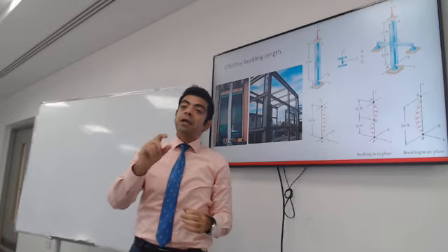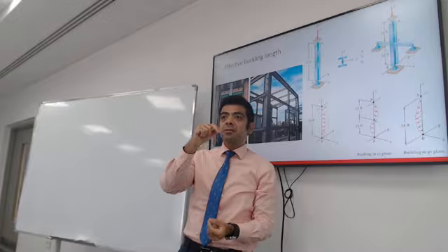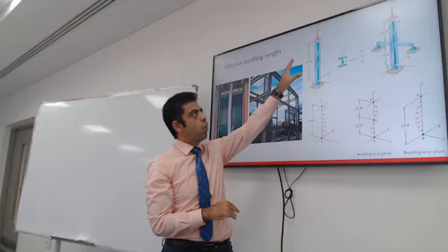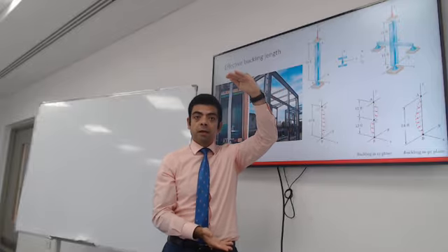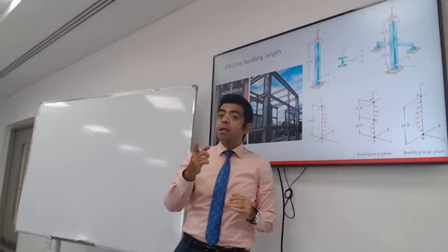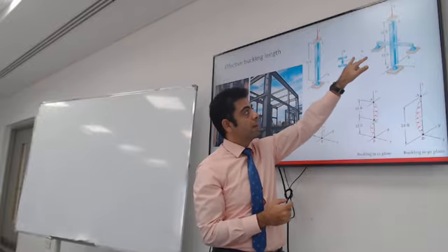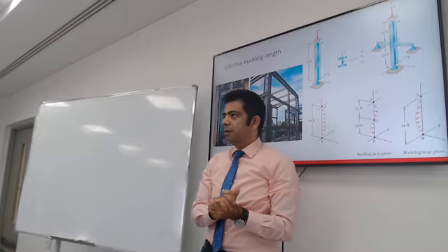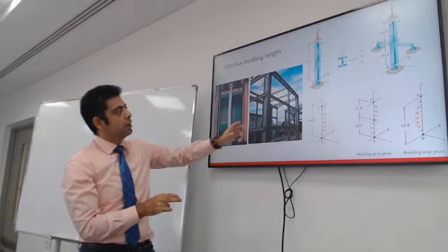If you go through the calculations we did last week to calculate the axial capacity of a column of 7 meters, you will find that there is quite a bit of a reduction because of buckling, because of the tall length. A way to help that section is to brace it with lateral beams. That will decrease the effective length. All right? So let's take a look here at the buckling length.